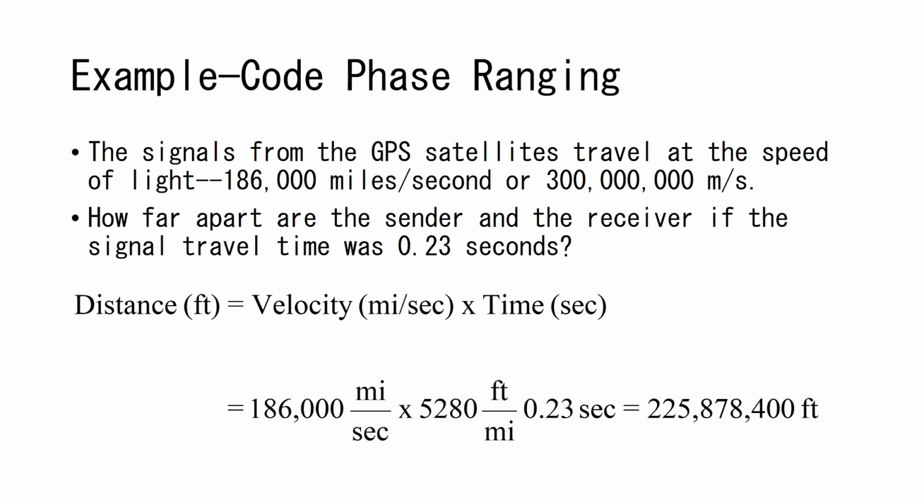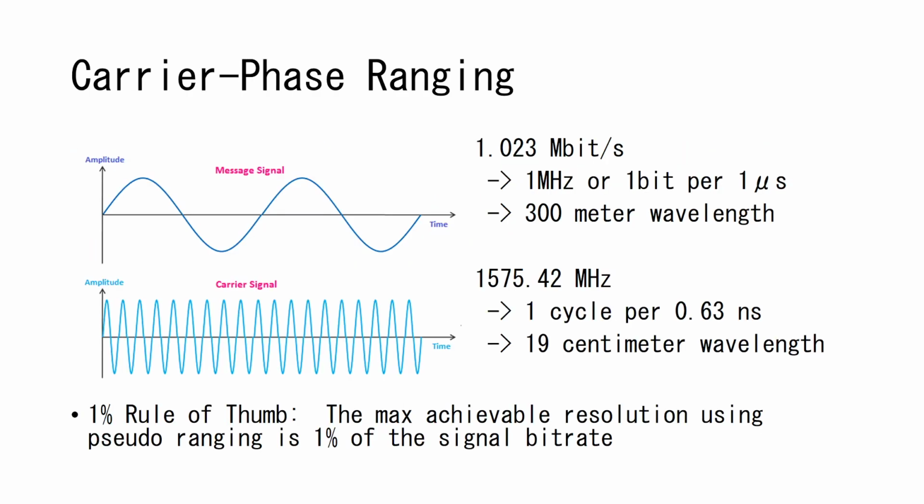Now that works great for many different cases, but carrier phase ranging is something we see that was originally very popular, especially in surveying types of receivers, because we need a lot more precision. But we're seeing this in a lot of things nowadays. A lot of our receivers can utilize carrier phase ranging. And why do we even use carrier phase? Well, just to set up the reason for not just maintaining that code phase versus using carrier phase.